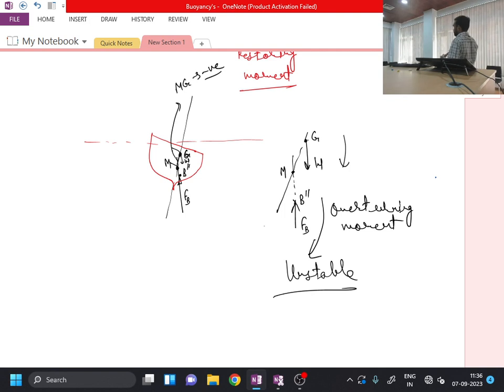Okay, because whenever you take water out of it, its weight will decrease, because the portion you have vacated by pumping water out of the submarine's tank is now taken by air, which has low density. So the total weight of the submarine will go below the buoyancy force acting in the upward direction, meaning the density of the submarine becomes less than the density of the fluid, and it will rise in the upward direction.